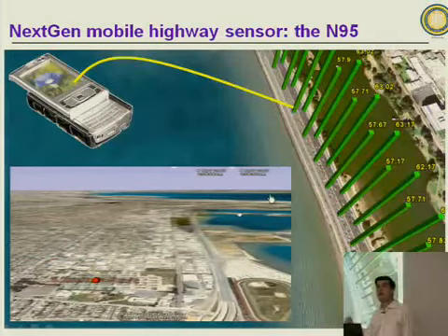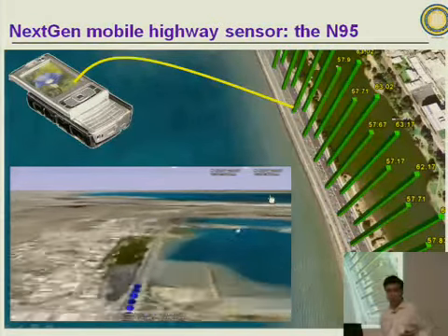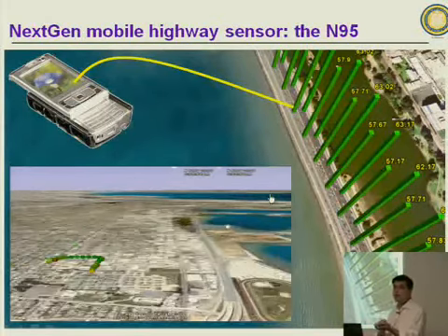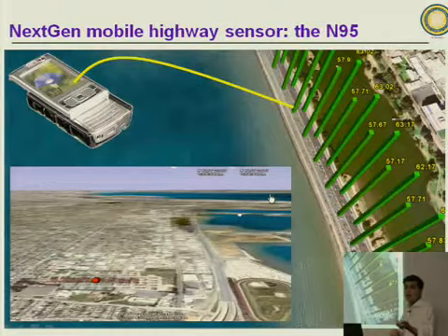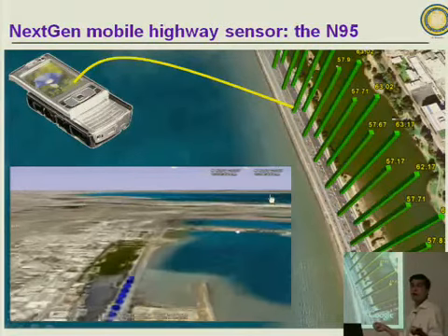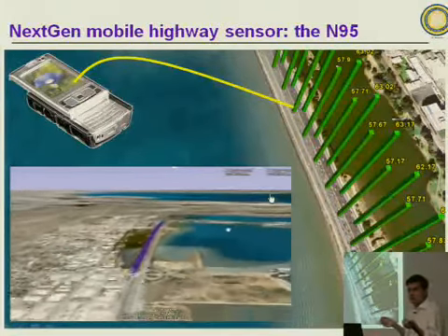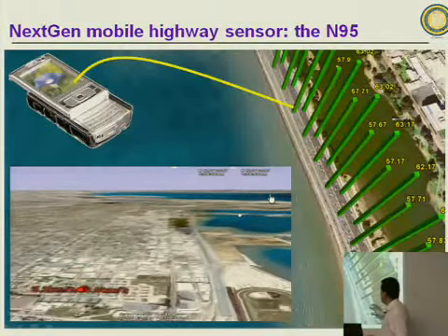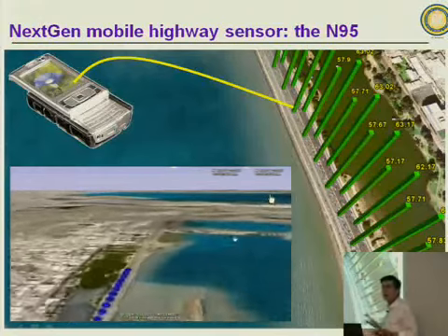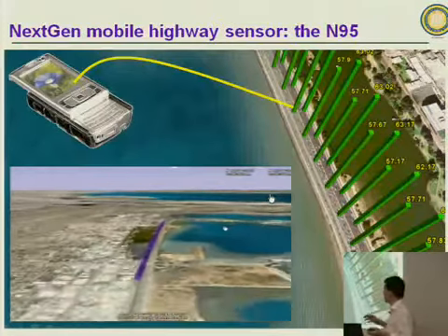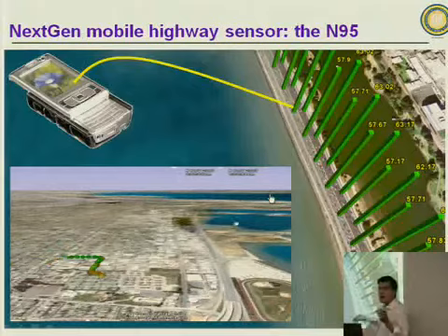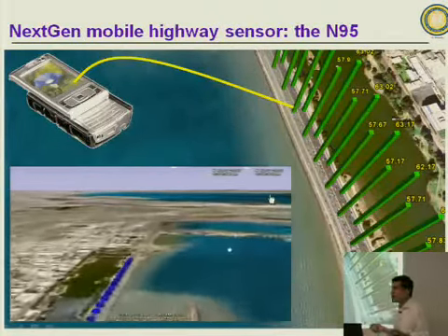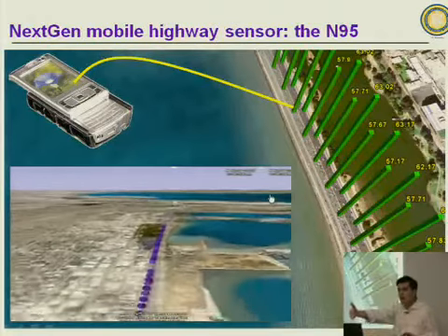And that's the main difference with triangulation or trilateration. In fact, if you download Google Maps on any of these Nokia phones, even if you don't turn the GPS on, you can find your position using trilateration, and usually the accuracy is about 1 mile or 1 kilometer, which is obviously disastrous if you're trying to compute speed, or even position, for figuring out occupancies on the highway. Clearly, compared to what has been available for the last 10 or 15 years with trilateration, we suddenly have a leap forward in terms of accuracy.